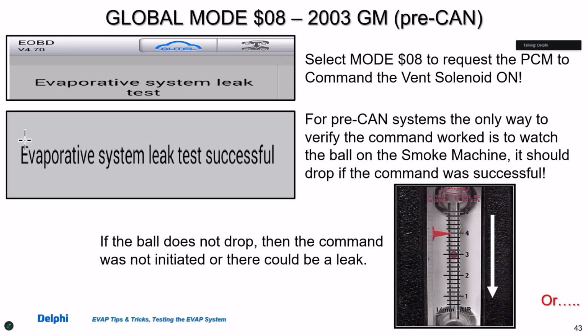Now, if you're doing this test and you take the scanner and you disconnect it, you back out of the test, whatever, with the key still on, that vent solenoid is still on.